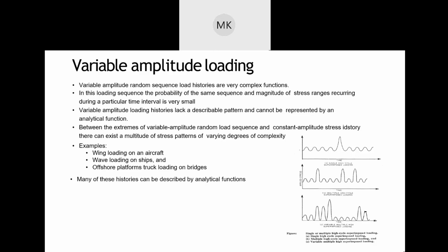So at the other times, both bridges are going to have a decent amount of crowd, but not as much as they're going to have in those 2 hour brackets. So that's how the variable loading works, and we want to make sure that the maximum load that happens in the variable loading is way below the constant amplitude loading strength of that material. So that's the major thing that you have to see.